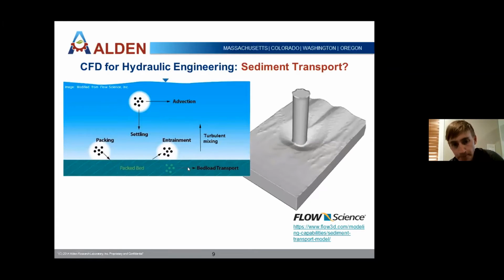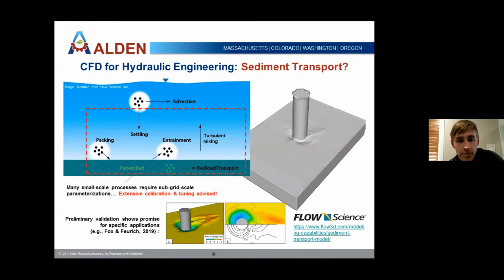bed load transport. And the entrainment and bed load transport are primarily based on empirical equations, based on lab and field work. So as I said, there are many small-scale processes going on that must be parameterized, these sub-grid scale processes. So I would definitely caution the user that while this is very exciting and cutting edge, extensive calibration and tuning of your model is definitely advised.